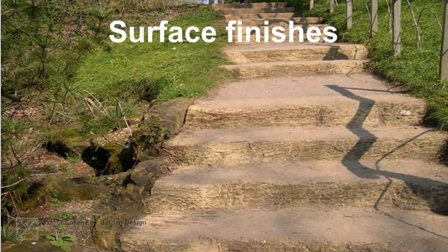Manual compaction of concrete with the edge of a timber board will often leave a slightly ridged finish to the surface of drives. This may be acceptable as a non-slip surface. Alternatively, a smoother sandpaper type finish can be obtained with a wood float or a steel float trowel. A fine textured non-slip finish can be applied to a floated finish by brushing with a stiff broom.